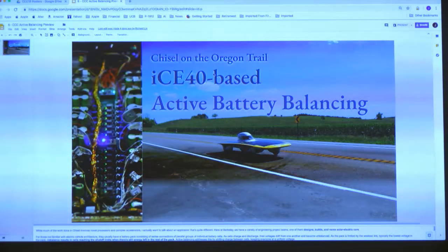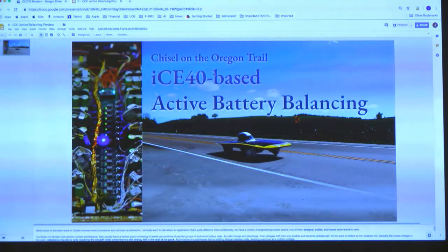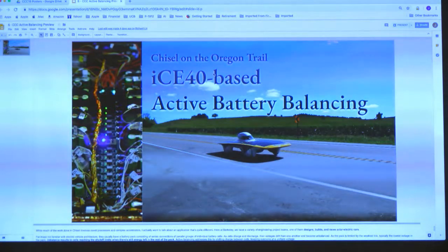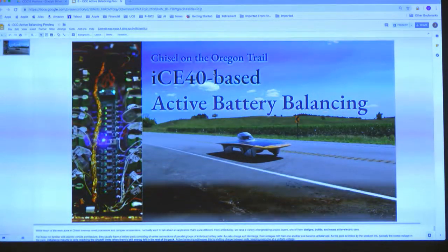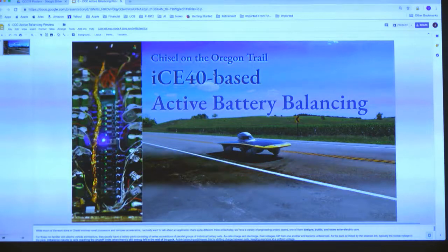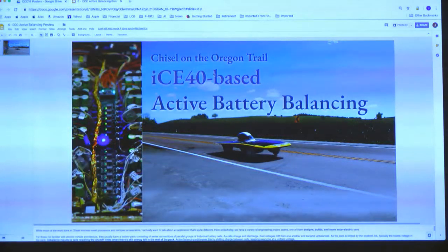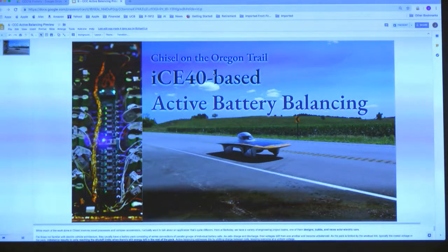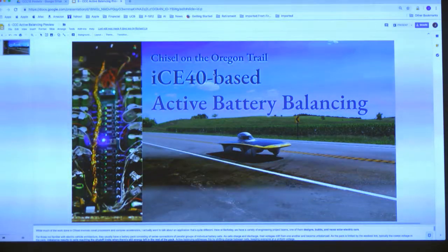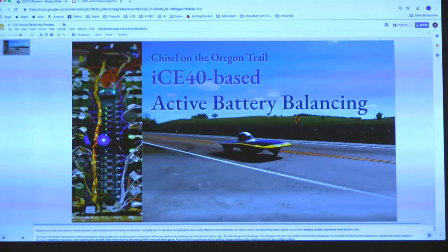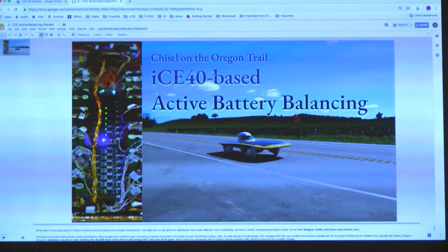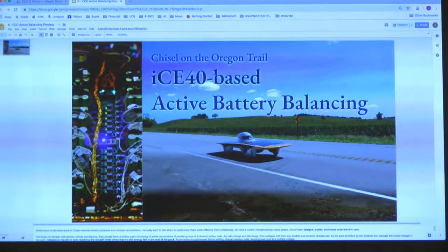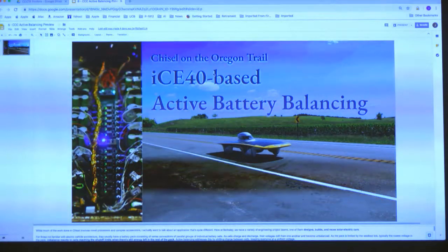The active balancing system we implemented consists of a power stage controlled by PWM generators on an ICE40 FPGA, selected for its ease of use and the existence of the fully open source Yosys toolchain. These are controlled by a microcontroller, which makes active balancing decisions based on sensor data from the rest of the vehicle, communicating through an SPI link, and all the RTL we built in Chisel. During development, use of Chisel provided many advantages over conventional languages.